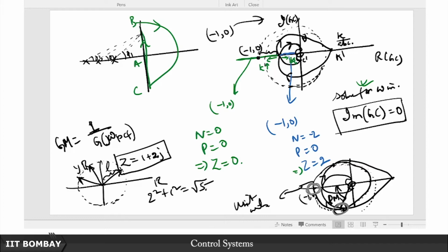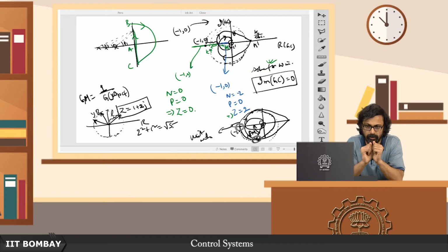So from this Nyquist diagram, by just looking at the unit circle intersection and the intersection with the negative real axis, I can actually figure out what my gain margin and phase margin are. Again, caveat: we are only talking about open loop stable systems, where it makes sense to talk about positive gain margin and phase margin as something desirable. So that is the interpretation.